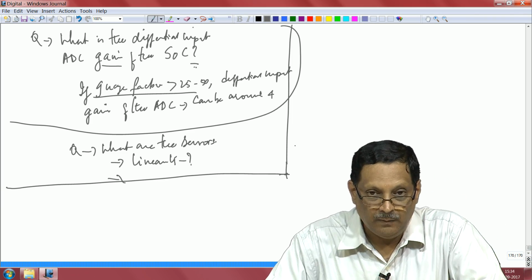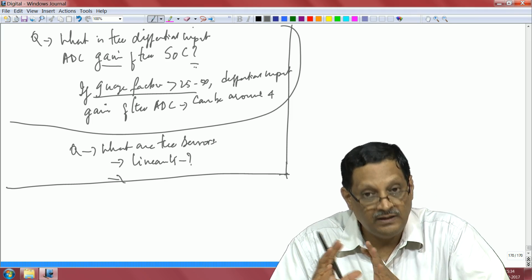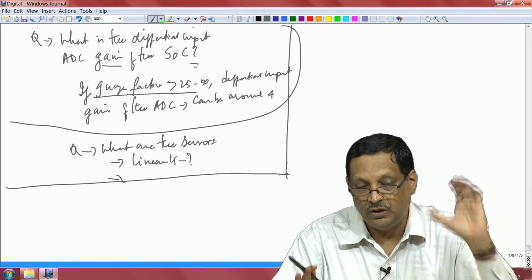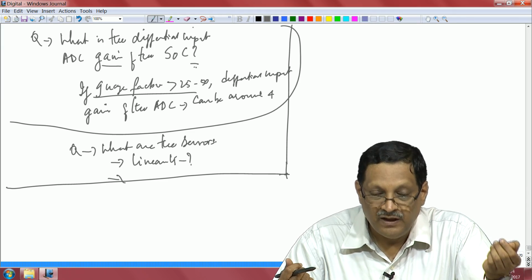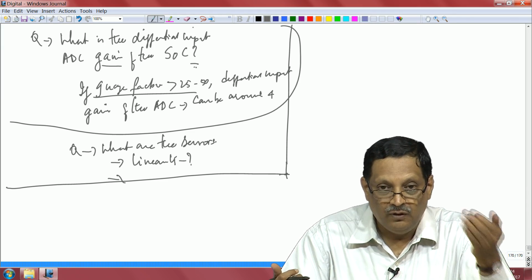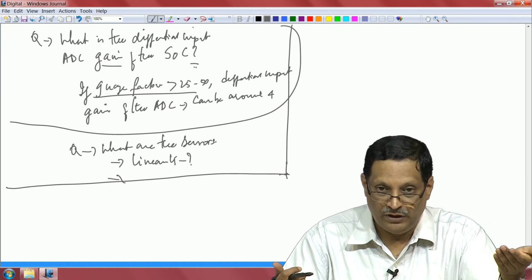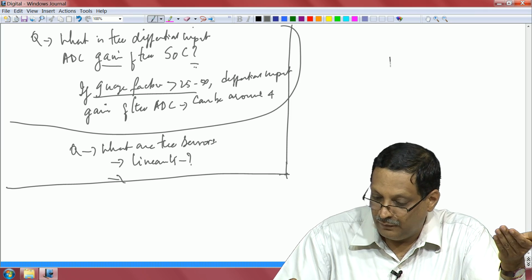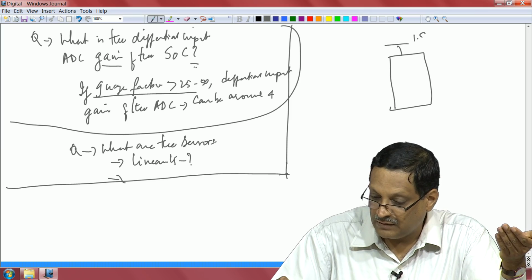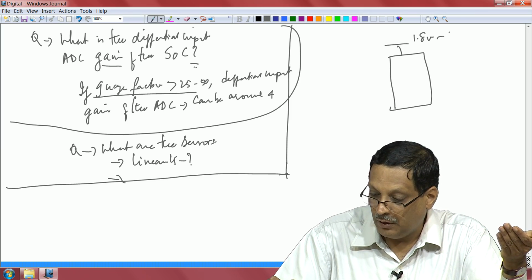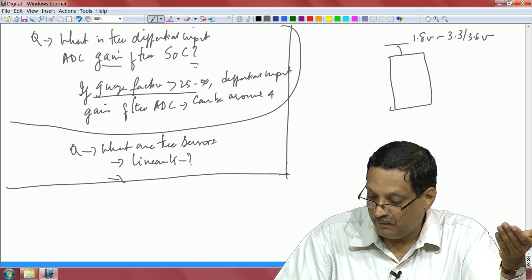Another important thing, I mentioned to you about excitation voltage for the strain gauge, excitation voltage across the strain gauge. It is also important that the microcontroller itself works over a range of input voltages. For example, you can have a microcontroller which works from 1.8 volts up to about 3.3 or 3.6 volts. Okay.